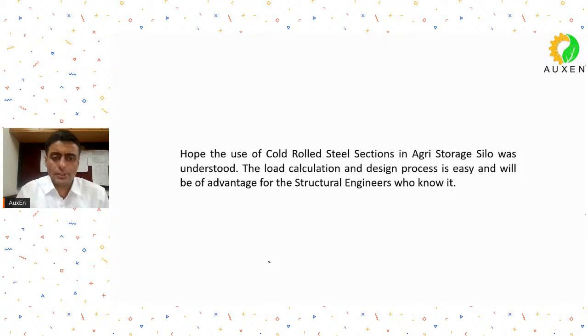So I thought I'll just tell you this because it is an interesting avenue for structural engineers to work in. Right. Very interesting. Mr. Kashyap is asking about the connection to RCC, is it pinned? Yeah, because you just put simple bolts, you don't have a big anchor bolt and all those things. You try to create a simple pin assembly. And anyway, because all those members are so closely placed, you don't get a very large moment magnitude.